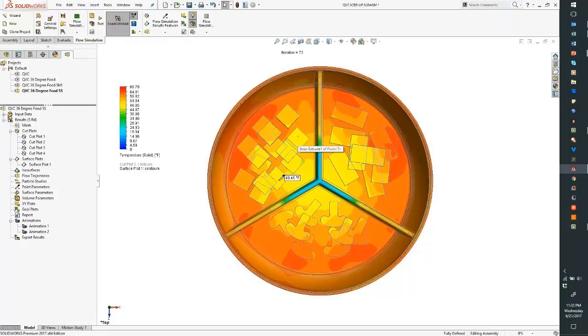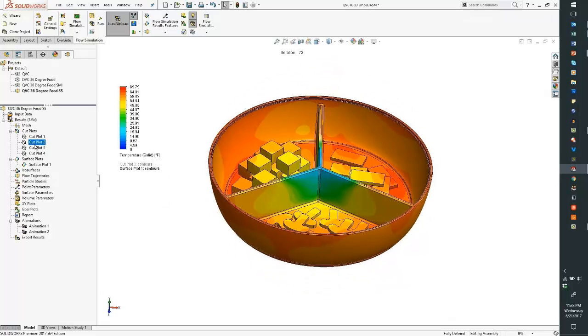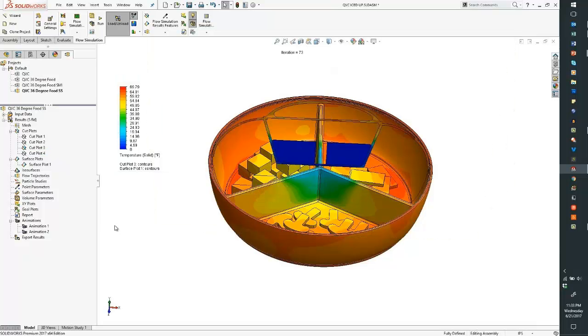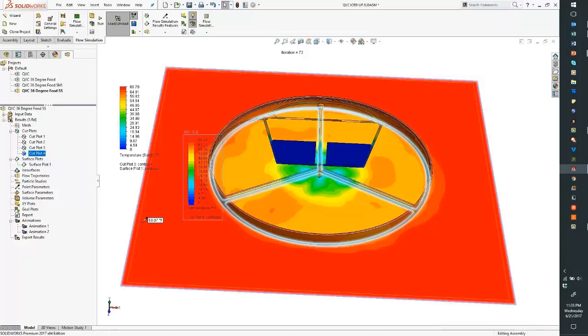And what we see is they are lower. They are lower than where I solved through with transient, but not much lower. You can see that the ribs there definitely cooled down, but we still have that one cold column of air in the middle, and on the outside, you can see we're still at 60-some degrees. So it leads me to the conclusion that this may not be the best or most efficient way to do heat transfer for this type of device.